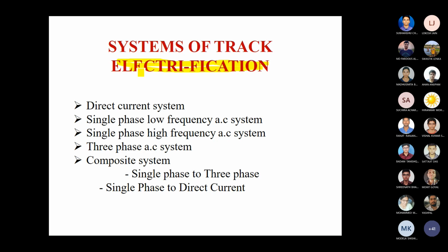And the SF6 circuit breaker is not so common. Where do we use SF6 circuit breakers? We use them for substations, especially transmission substations. But in this railway system you are not using SF6. The vacuum circuit breaker and the air blast circuit breaker are both more than sufficient for breaking the circuits. These are the very basic concepts for electrification.